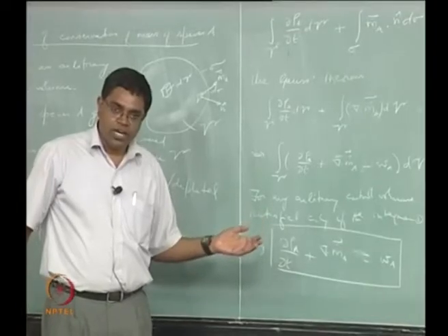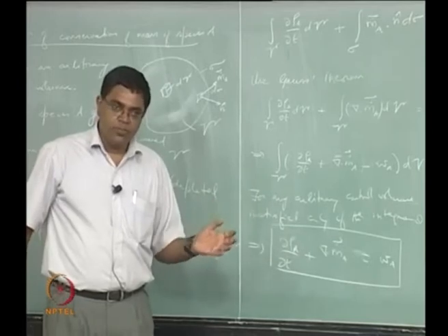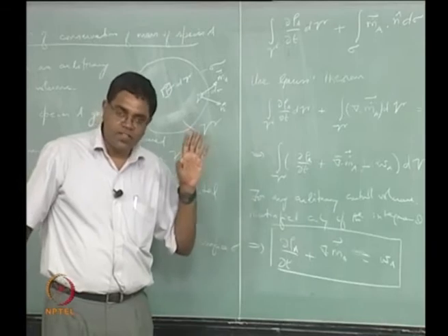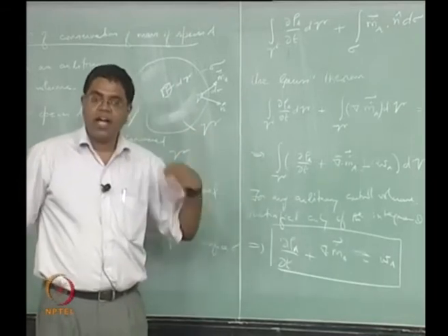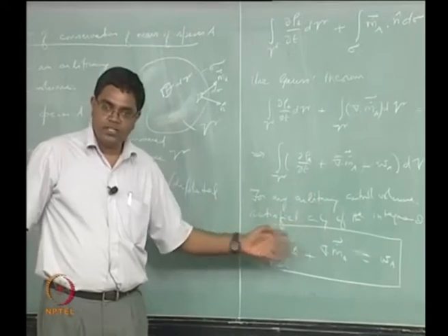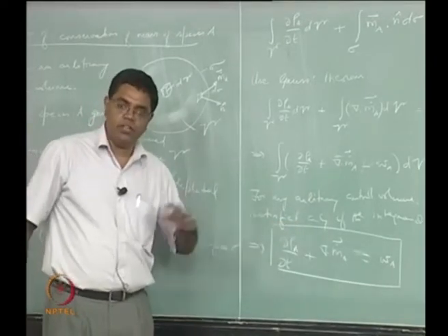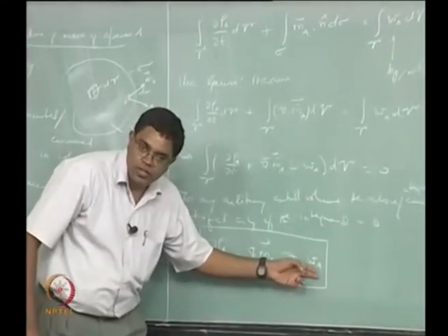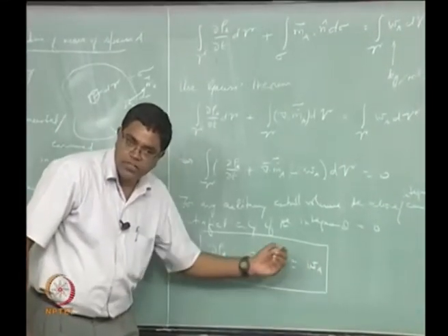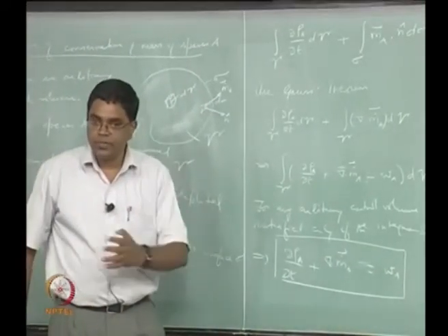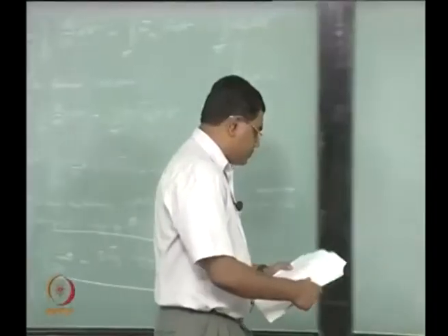And then we will now have to split it into the mass average velocity of the mixture and its diffusion velocity. When you do that, we will get a convective term and a diffusion term separately, in addition to the reaction term that's showing up already. Then we will begin to see the three basic processes: convection, diffusion, reaction. So that's where we are heading.